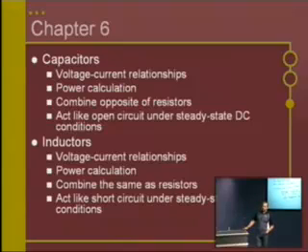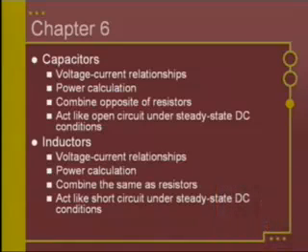Probably the most key thing to take away from the chapter is what is the behavior of a capacitor and an inductor under DC conditions. The capacitor acts like an open circuit. The inductor acts like a short circuit. So those are the key things there, I think, more than anything else.